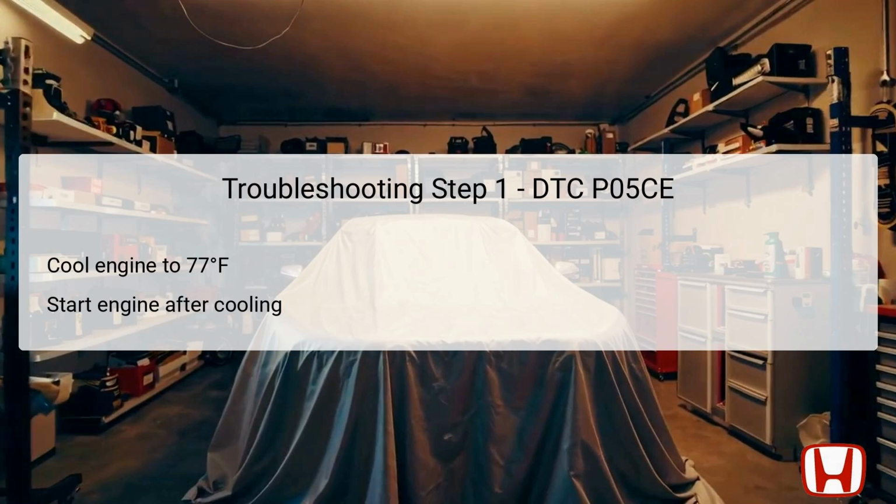Once the engine has reached the appropriate temperature, the technician can start the engine to begin monitoring its performance. During engine startup, it's crucial to observe the initial behavior and listen for any anomalies, such as irregular sounds or vibrations that could indicate underlying issues. Ensuring that the engine is at a regulated temperature helps to eliminate temperature-related malfunctions that could lead to false DTC readings. This step is fundamental for accurate subsequent diagnostics.